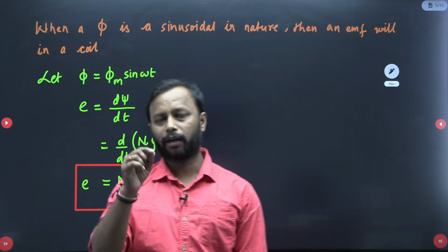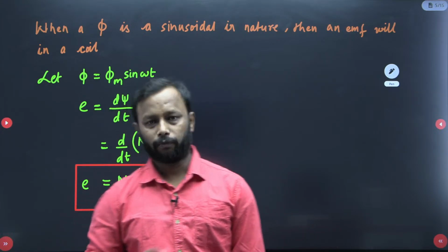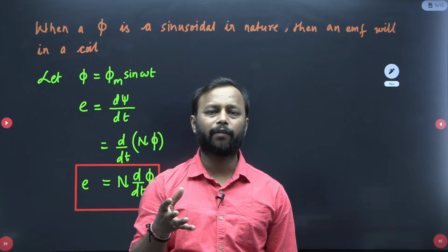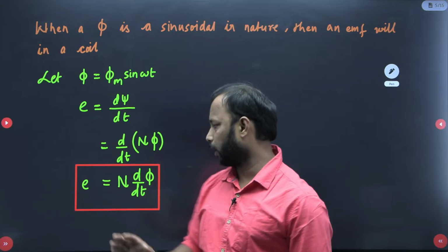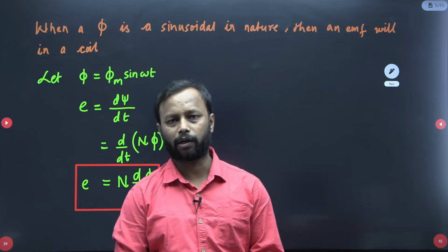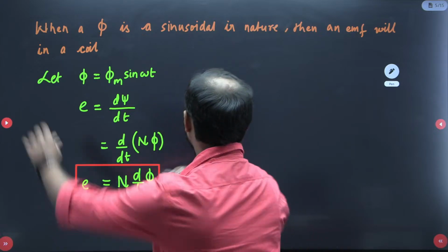ठीक है? तो इसीलिए करंट को क्या लेते हैं हम लोग? ऑल्टरनेटिंग. We are not going to take the DC current, because for the DC current the magnetic flux is also going to be constant and it is going to give you EMF as 0. Therefore transformer will not going to work. So let me write a point here.